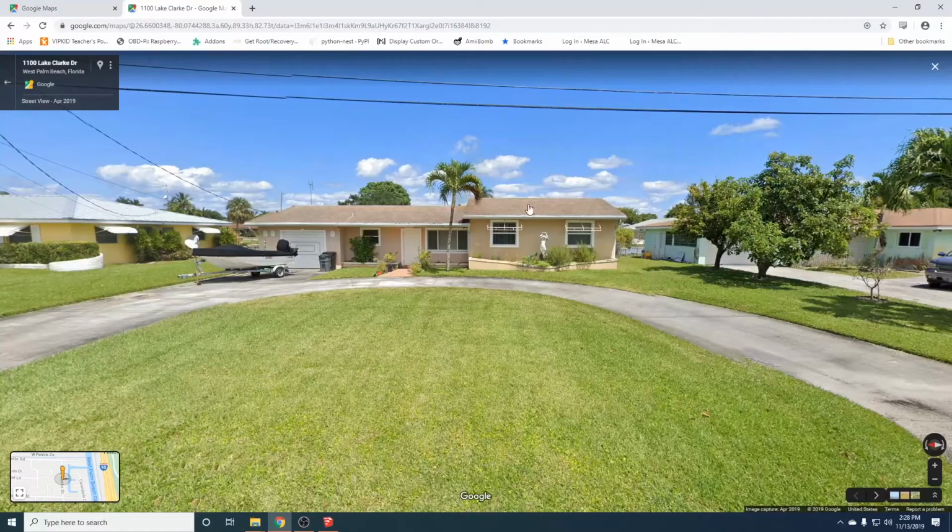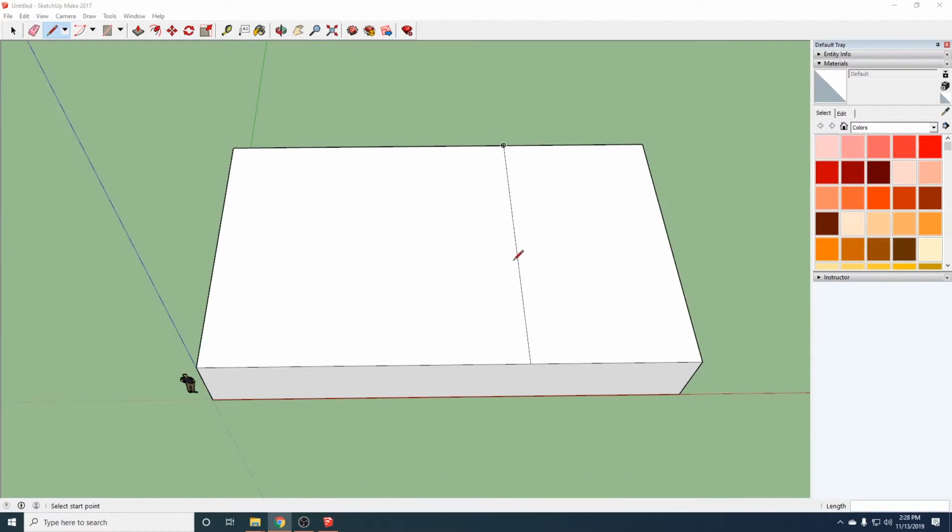Now this roof line also is just cut right down the middle on both sides, and the slope comes off evenly on either side of the house. So we'll just draw that middle line. Now not only do you snap to lines and endpoints, you'll also snap to midpoints. The midpoint snaps to that teal color there. So we can just start right here on this midpoint, click once, and start dragging out. In this case, we want to have a line that matches this red axis here. So we'll just draw it out till we hit the midpoint of that,